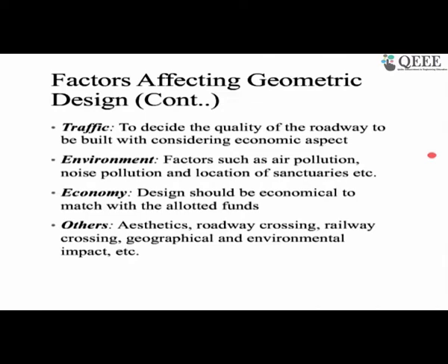If your new highway is passing through a community, and high-speed vehicles are going to go through, they are going to honk, and the road-tire interaction is going to make noise. How this noise is propagating and affecting this community, whether it is going through some environmental area, and how it is going to affect it. These are the factors. So if it is going through a community, you may need to provide a noise barrier and so forth.